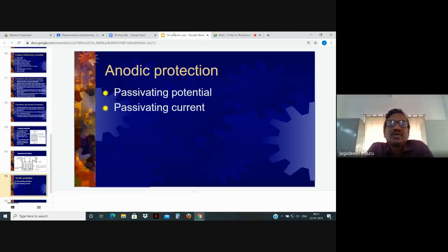For another purpose, in R&D we find a passivating potential and passivating current. So what is this passivating potential and current? You take 2 bars of any unknown metals and connect them in an electrochemical reaction using the galvanic cell concept, by putting them in an electrolyte solution, that is, a dilute acidic solution, and giving a connection. You are bound to get some electricity generated, which you can note by using an ammeter and voltmeter. We will be able to know how much voltage is generated in that particular combination. It means this much current is bound to be present when the corrosion reaction is progressing.